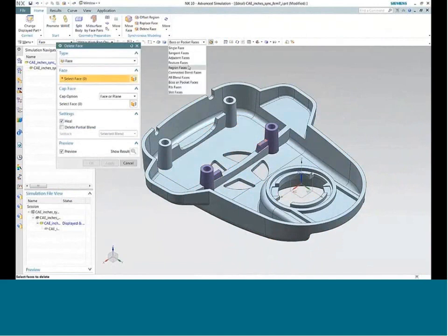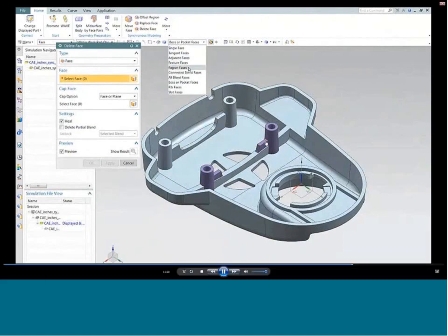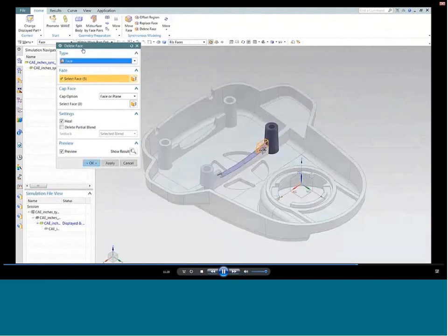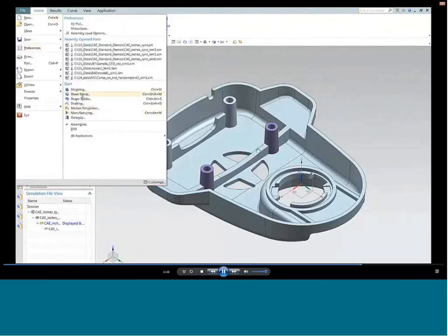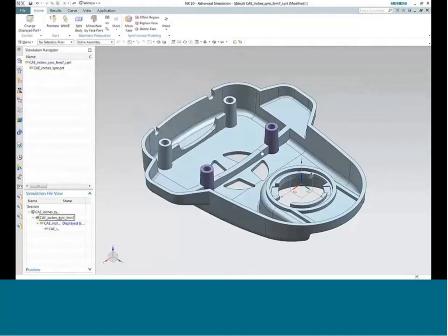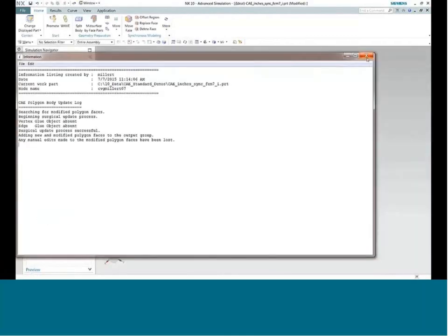And just to make things look a little bit more nice and neat here, I'm going to delete these little tabs that stick up just so that the surfaces are a little bit more streamlined. So I use the delete face synchronous modeling command to do that. And you'll notice just by clicking the one face on each of those two little tabs, I delete the whole thing, and it doesn't in any way interfere or corrupt the underlying geometry itself. It just deleted those tabs that stick out above the rib.